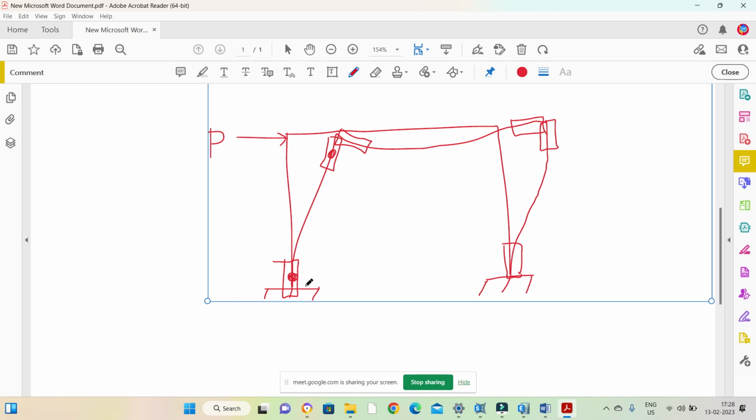So to simplify that, we apply our fundamentals and roughly predict where the failure can occur. There only we provide the nonlinear definition, so that we can reduce our analysis time, and the software can at least analyze the structure. Because if we unnecessarily complicate the structure, the software sometimes will not be able to run the analysis. It will not converge, so it will show an error.